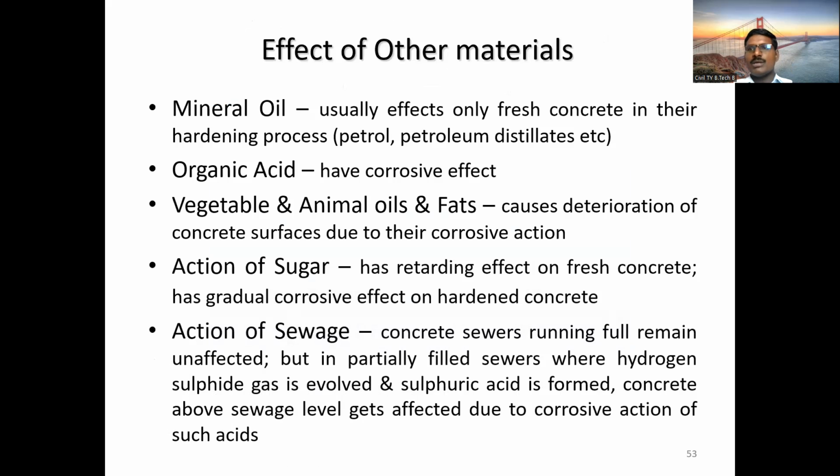Then the impact of other material. What other material impacts the durability of the concrete? Mineral oils usually affect only fresh concrete in its hardening process. Petrol, petroleum will affect the fresh concrete.